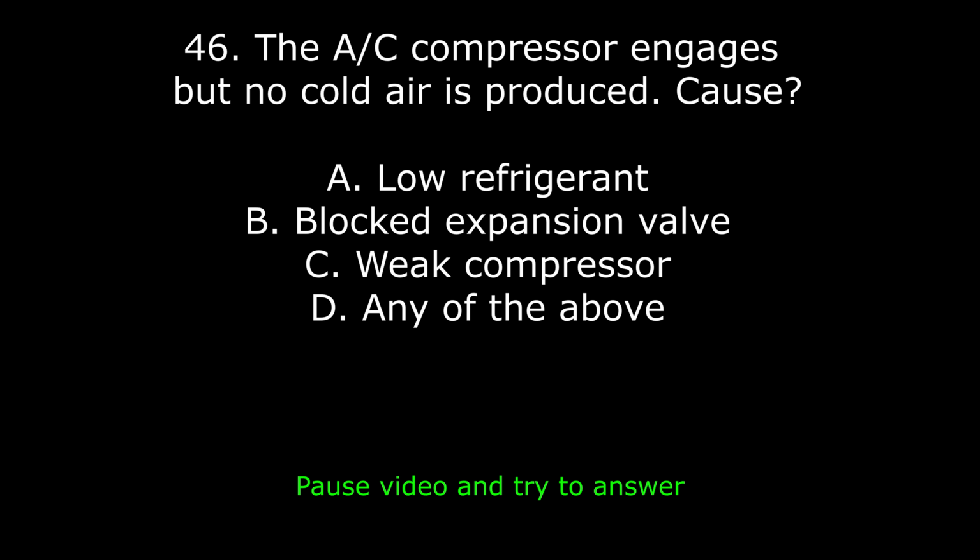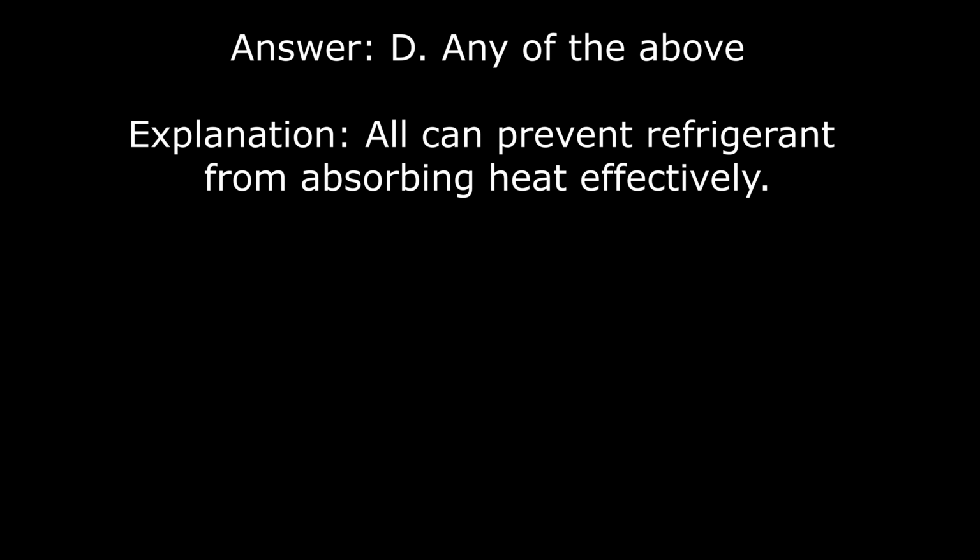46. The AC compressor engages, but no cold air is produced. Cause: A. Low refrigerant. B. Blocked expansion valve. C. Weak compressor. D. Any of the above. Answer: D. Any of the above. Explanation: all can prevent refrigerant from absorbing heat effectively.